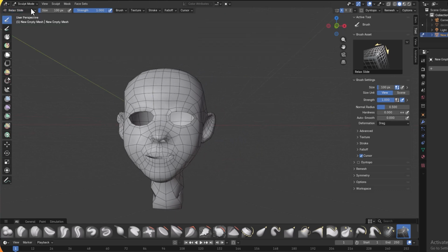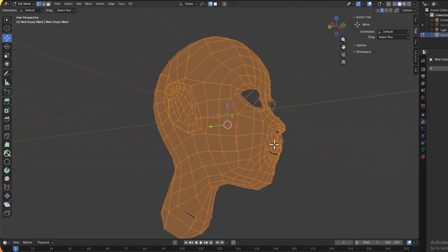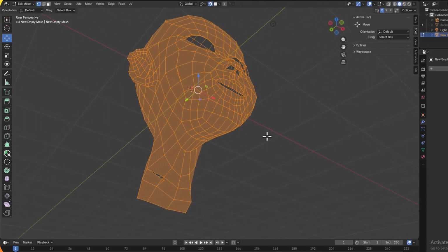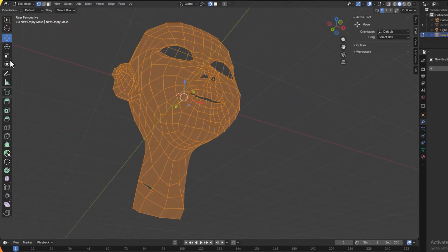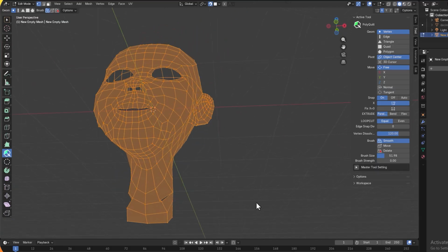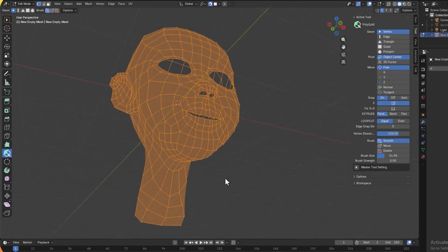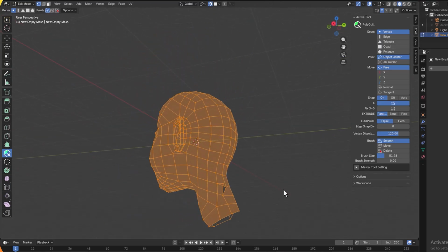So come back to the edit mode again and try to look at the problem we have here. I need to change this to pole, which we are done, and I'll select this width, and with the hold of shift I'll drag it through there and fix the broken edge for the edge loop.